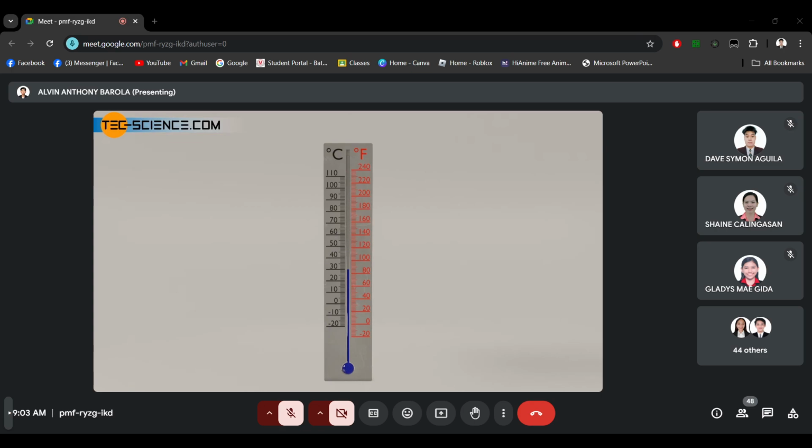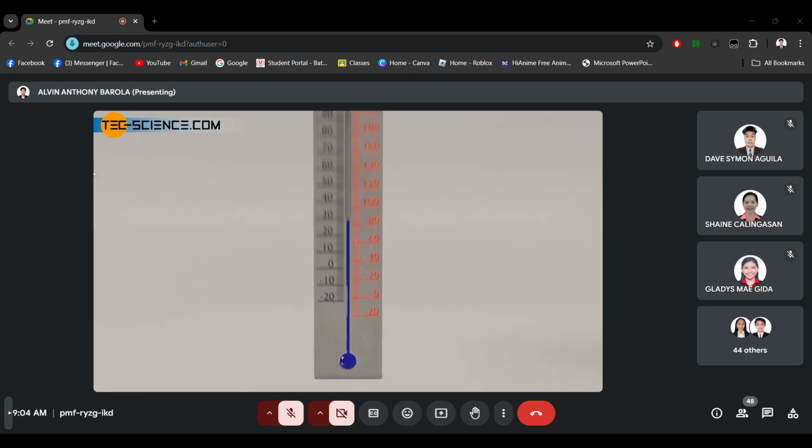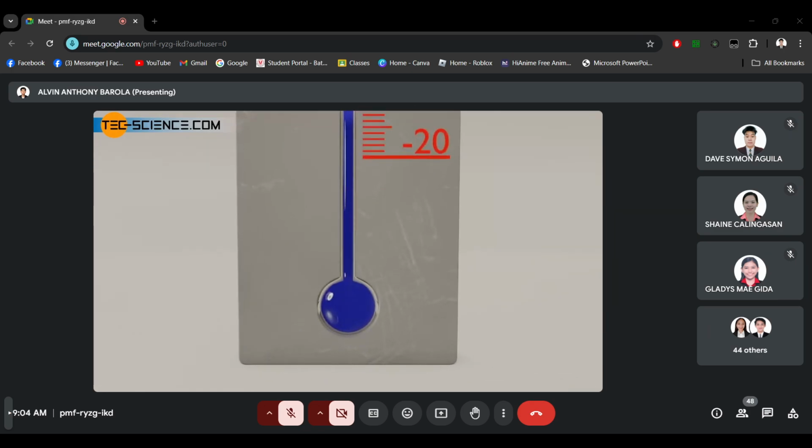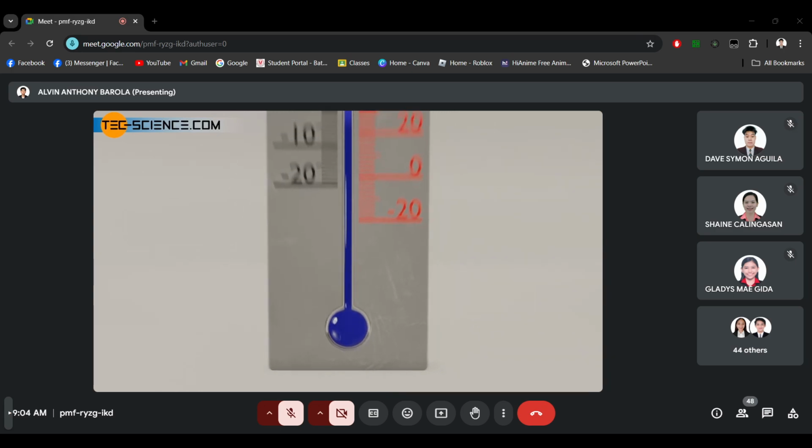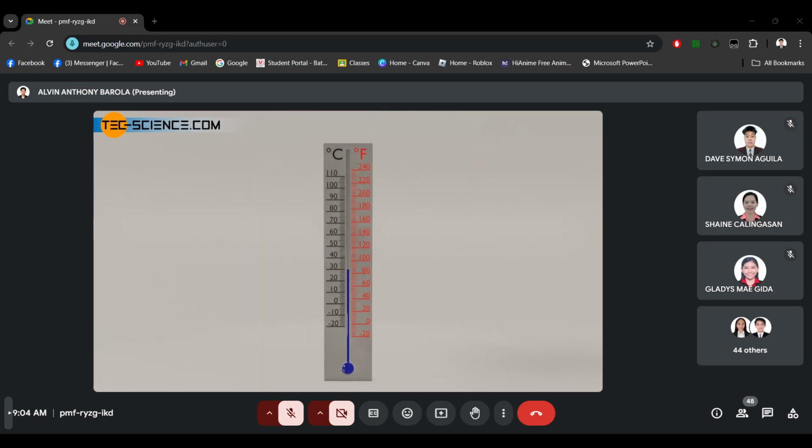well covered. The measuring sensitivity of liquid in-glass thermometers increases with the amount of liquid in the thermometer. The more liquid there is, the more liquid will expand and rise in the glass tube. For this reason, liquid thermometers have a reservoir to increase the amount of liquid in the thermometer. Too much liquid, however, would cause the thermometer to react very slowly to temperature changes, as the heating of the liquid will take longer and the liquid will take longer to adapt to the outside temperatures to be displayed. Thus, the reservoir should not be too large, but also not too small.